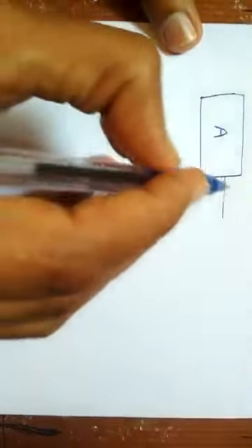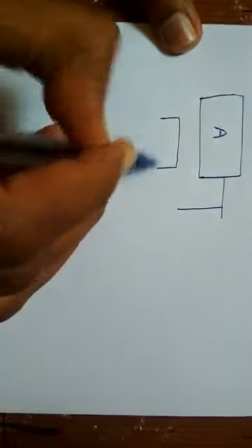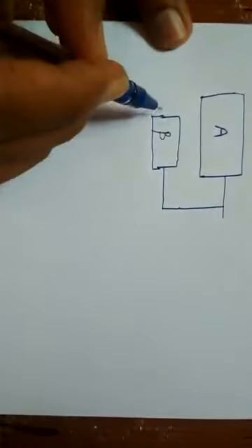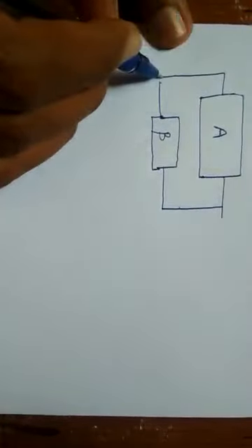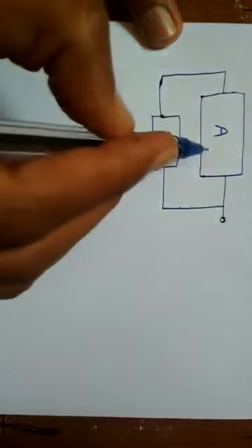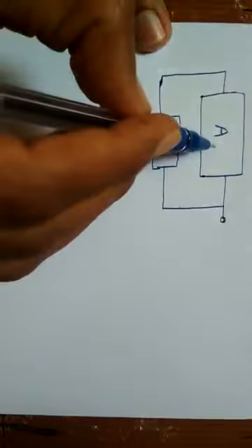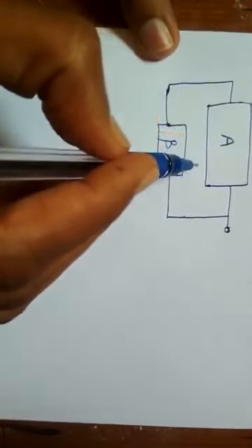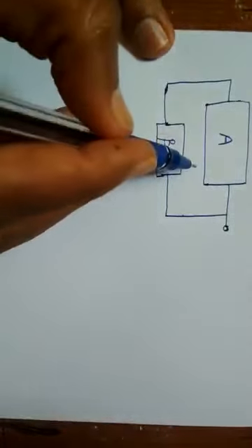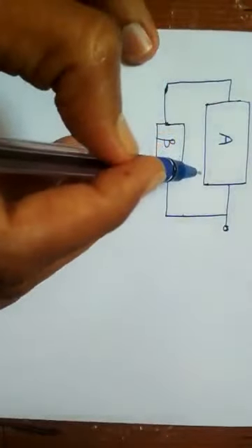So treat this as an amplifier with the gain of A in its forward path, and if we connect a feedback network with the gain beta to this amplifier, and the output of the feedback network is again given as an input to the amplifier, and after satisfying a criterion named Barkhausen criterion for this network, then this network becomes an oscillator.